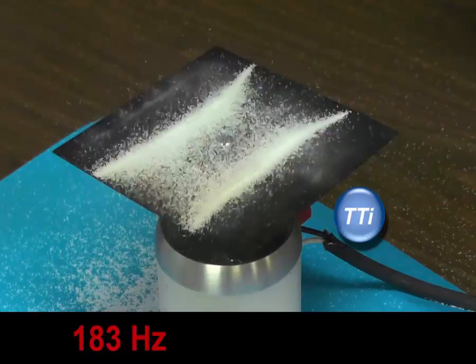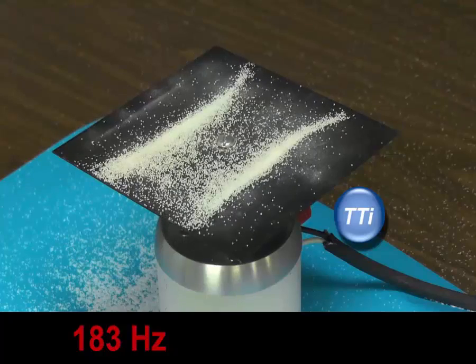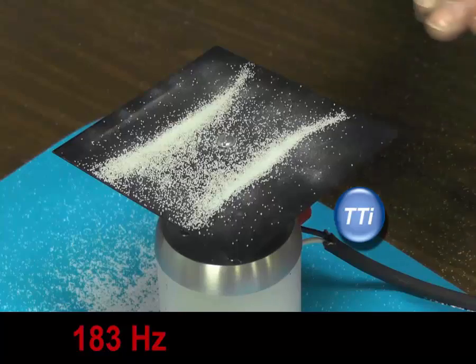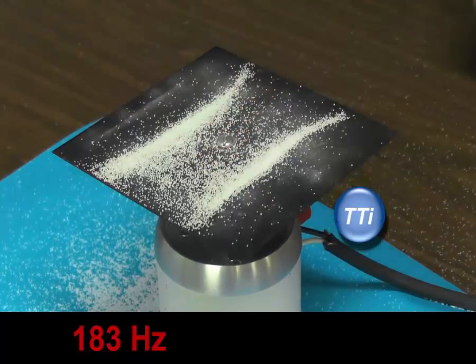And we can see two node lines, one across here and one across here. What's happening is this plate is now acting like a beam that is bending, and these are the node lines coming across here.